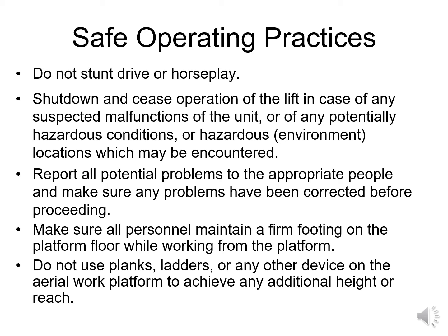Report all potential problems to the appropriate people and make sure any problems have been corrected before proceeding. Make sure all personnel maintain a firm footing on the platform floor while working from a platform. Do not use planks, ladders, or any other device on an aerial work platform to achieve additional height or reach. If we need to get higher, we need a lift that goes higher.